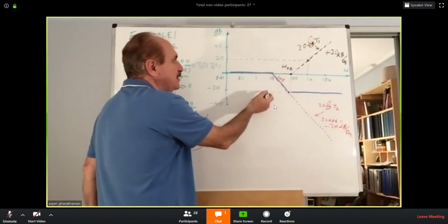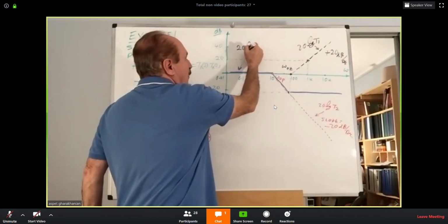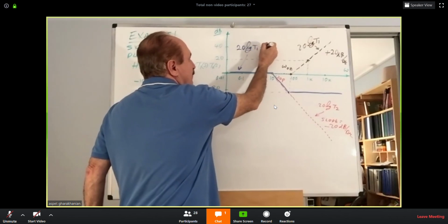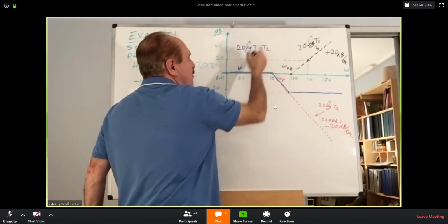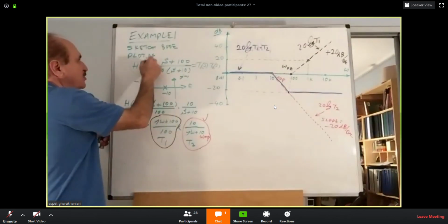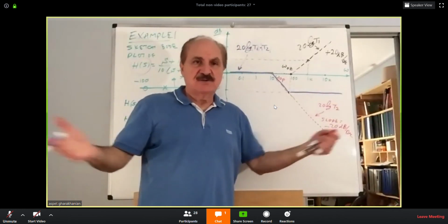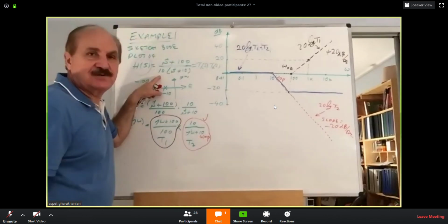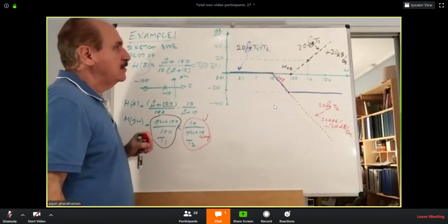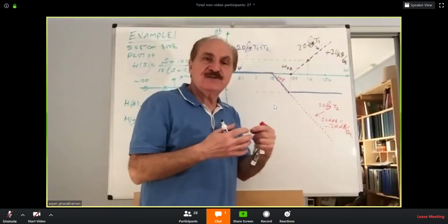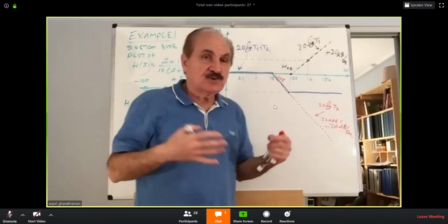So the blue one is indeed what you have here: 20 log of T1 multiplied by T2, the magnitudes. And by definition, this is the whole transfer function. So we got the blue one as the Bode plot of this complex function when presented as a J omega. So you see why it is so convenient to deal with the lines. That's why it is so popular.